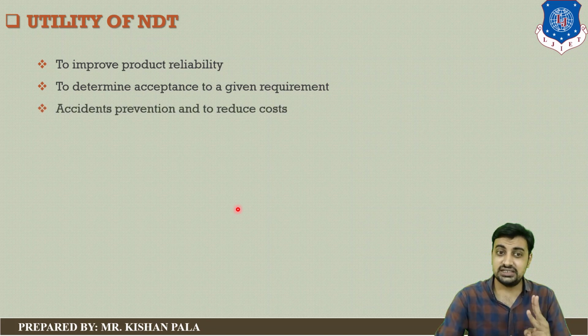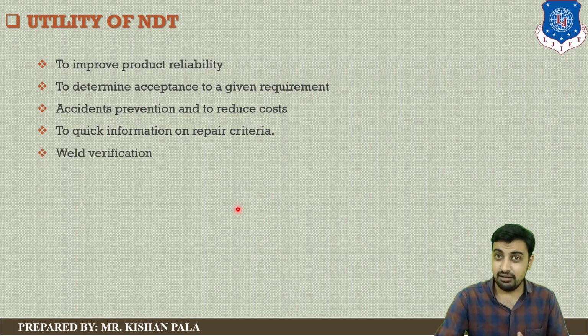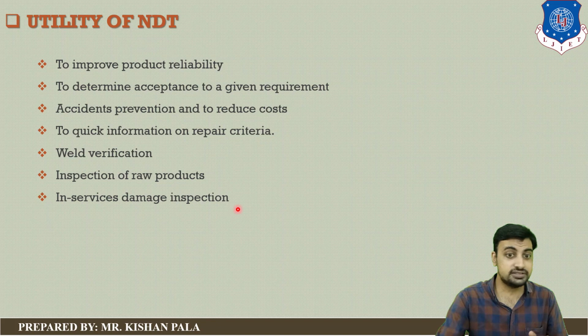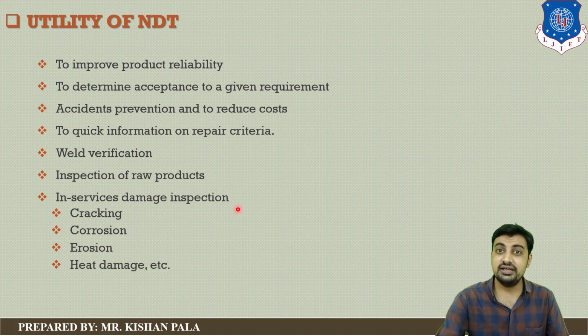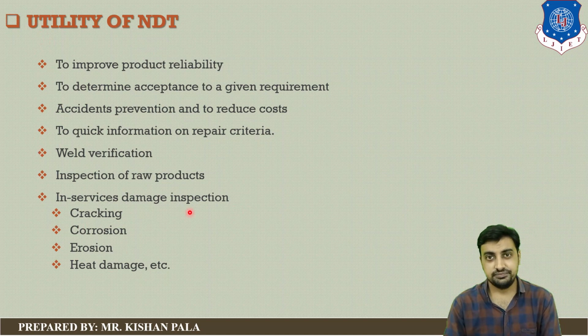The third one is accident prevention and cost reduction. The fourth one is quick information on repair criteria and weld verification, inspection of raw products, and in-service damage inspection like cracking, corrosion, erosion, and heat damage, etc. So these are the utilities of non-destructive tests.